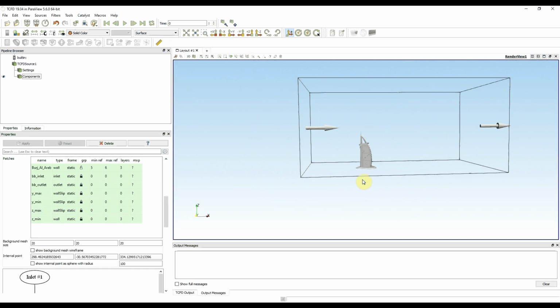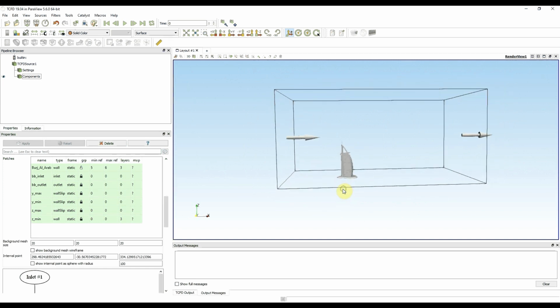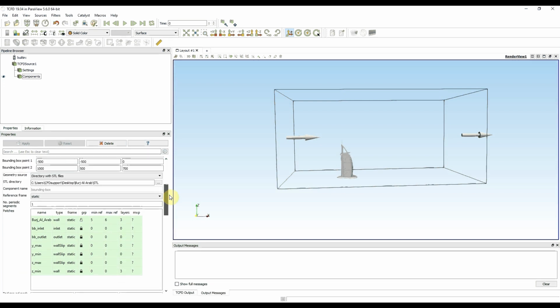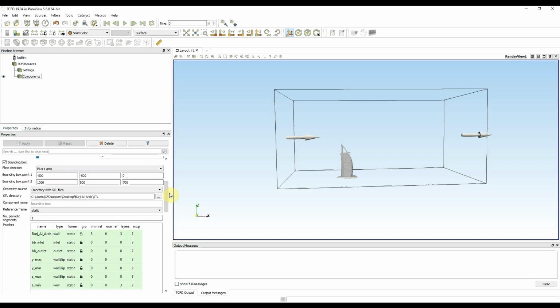But what's very important is the fact that more important than refining mesh is the size of the computational area. With small computational area, you will not able to get proper results. The size of computational area is very crucial because it influences results a lot.